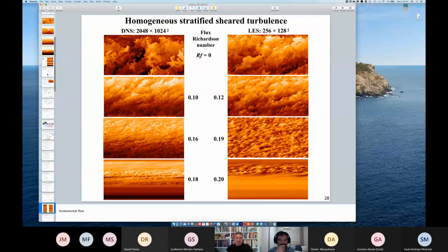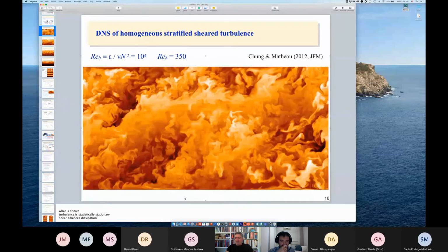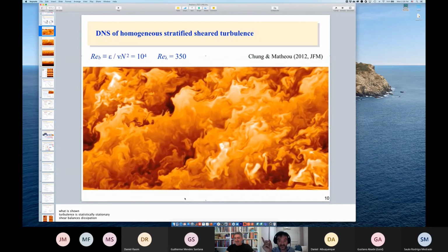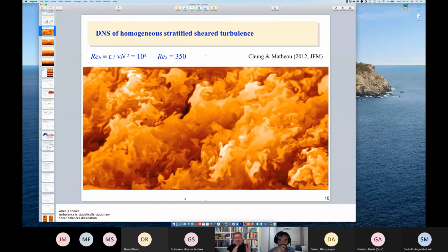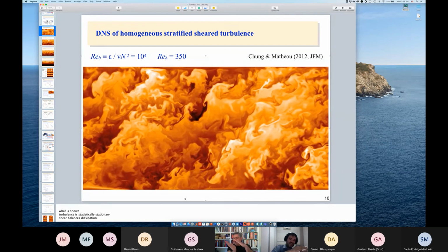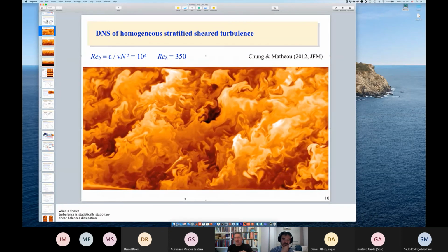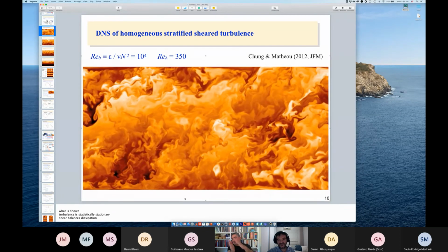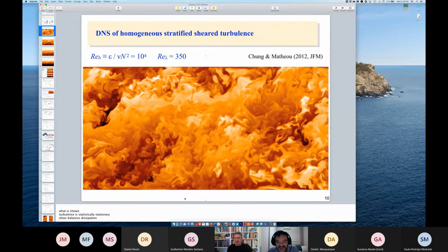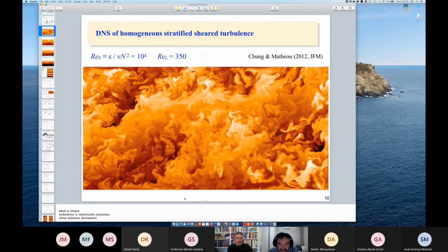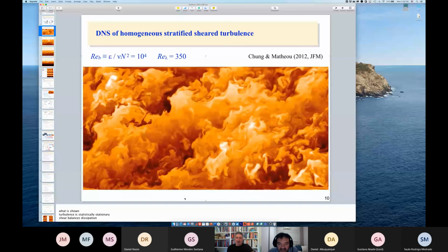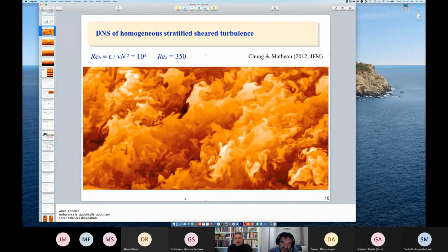What happens here is what we call shear periodic. So it's a grid that is actually getting sheared, the grid itself. It's Lagrangian. Yes, the grid is getting sheared with the flow. And then at every time step, we regrid on the vertical, because if you keep the distortion, it doesn't work for a long time. This is how we do it. So it's actually shear periodic. The grid is doing this, and then we regrid on the vertical at the end of the time step and do it again.